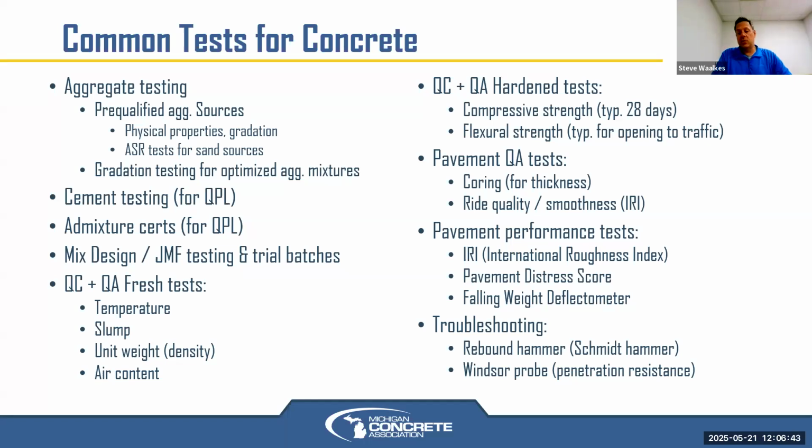The majority of the aggregate sources in the state participate in that if they do supply any MDOT work, because it makes sense, because they can get fewer frequency of testing than if they did not participate in that pre-qualified aggregate source program. They test for gradation, physical properties.